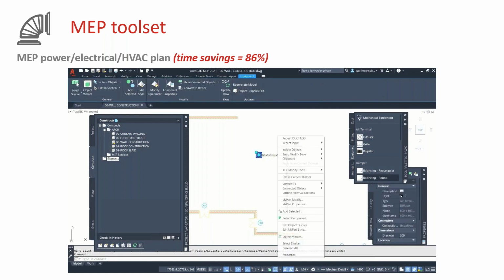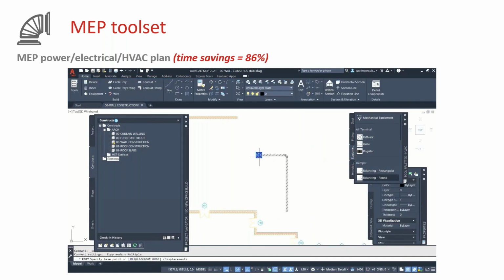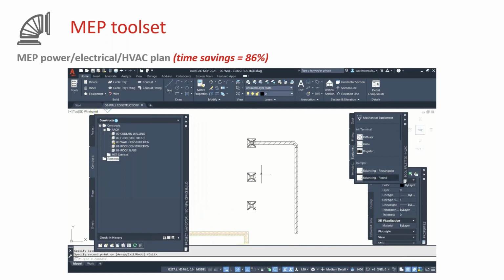Now, the other benefit I've got is I've still got my basic modify tools, things like move, copy, rotate. I've also got AEC modify tools. So I can do an array if I wanted to. I'm just going to do a quick copy. I'm just going to pick a point on the diffuser and drop a couple of other diffusers. I'm not going to worry about the distances between them. Obviously, if I was working on a proper project, I'd worry about distances and spacing.